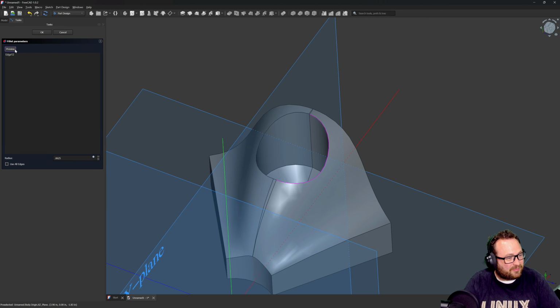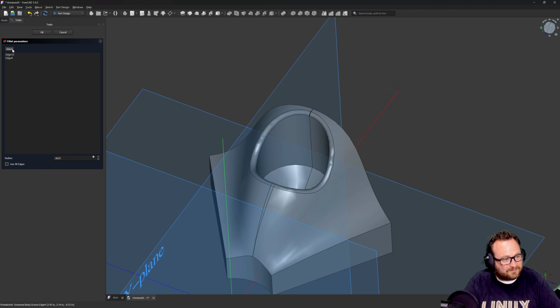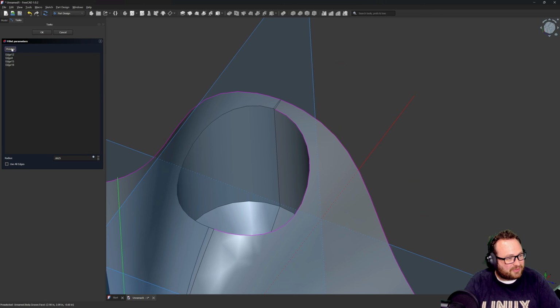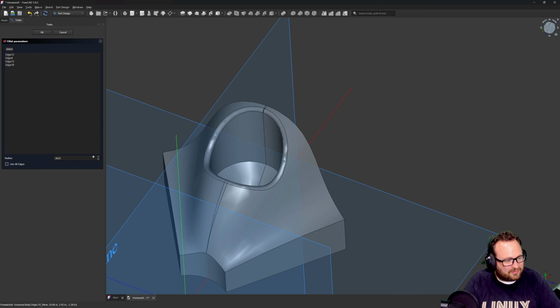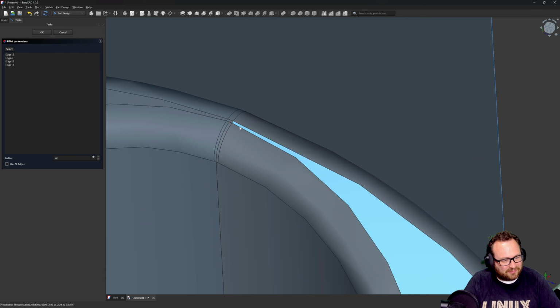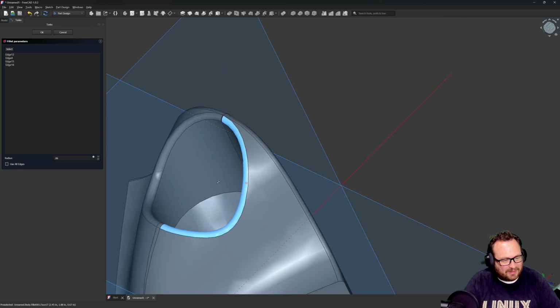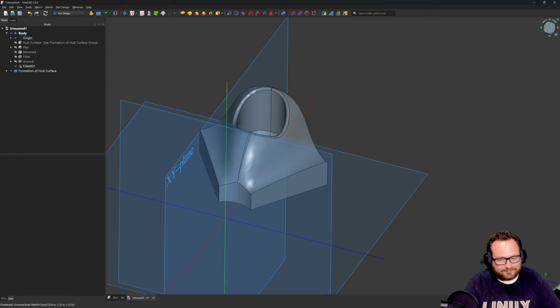We're going to go back to select and preview. Select again. I'll add this and this to make our fillets pretty clear. Preview. I'm not seeing that come through. Let's try 0.06 and see how that works. There we go. Yep, so I think our fillets were just a bit too big to show up, but we have those fillets. We're going to say OK.